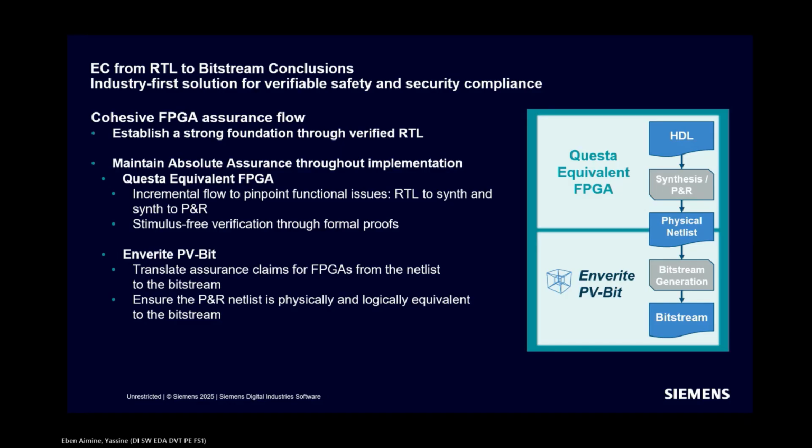It does already do some automatic partitioning within the tool, but you also have access to scripting that can do hierarchical partitioning, so you can black box certain things. You don't have to do all of the verification at the top level, at the device level. This can be part of a design and verification flow. We've got customers that do this as part of continuous integration.